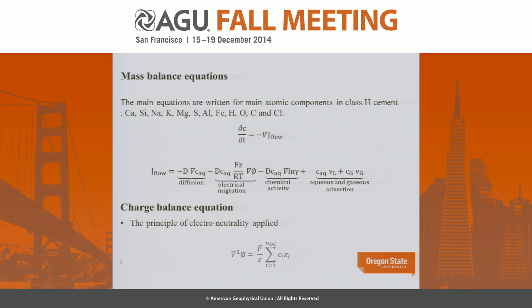So what was the tortuosity? We related all of them to the saturation degree of the system. Tortuosity has an empirical relation with the saturation degree, and saturation degree is related to the pressure gradient in the two-phase flow. So we applied all those equations.